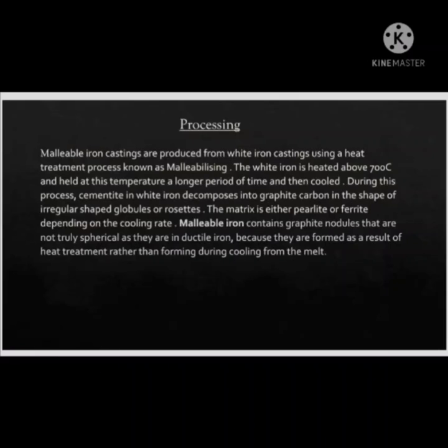Malleable iron contains graphite nodules that are not truly spherical as they are in ductile iron, because they are formed as a result of heat treatment rather than forming during cooling from the melt. So this is because they are cooled after a long time of heating.